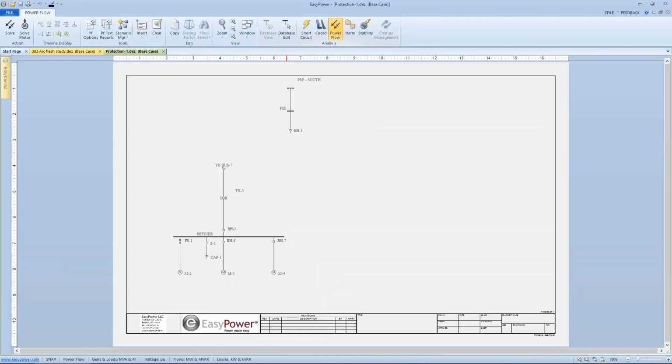Now go back to power factor and solve. And now I can see the effect of adding that capacitor on my power factor correction. Okay, you get the idea. The point is I can bring up very large drawings and then isolate on remote devices that have an interaction with each other, but may be graphically far removed from each other on the big one-line diagram. So I find this useful a lot, both in doing short circuit analysis when we're looking at coordination or we're looking at the sources of fault current, and especially in power flow.